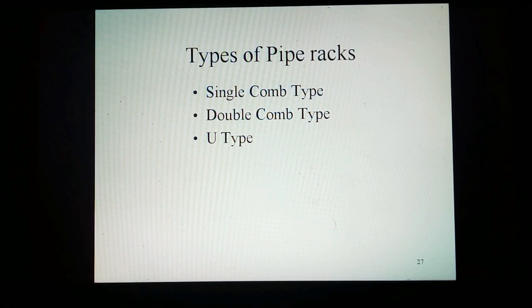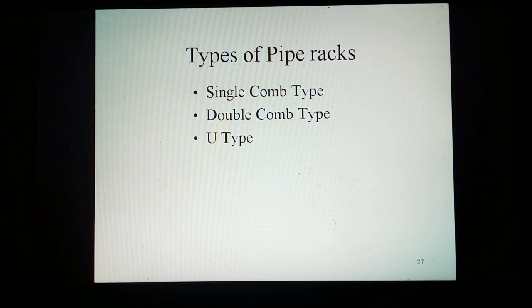Double cone type layout is an expansion of the cone type which is recommended for the use in large-scale process complexes where 5 to 10 process units are to be arranged. This layout can be conveniently utilized. U-type layout is recommended to be used in case of process units whose maintenance cannot be conducted separately within the complex. This type can be regarded as an expansion of the single rack type. Even process complexes of this nature can be regarded as one process unit in the planning of the layout.